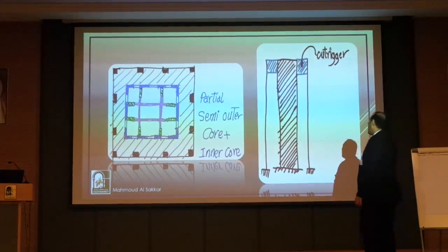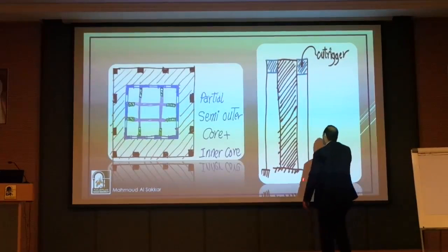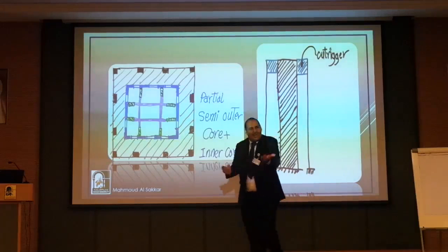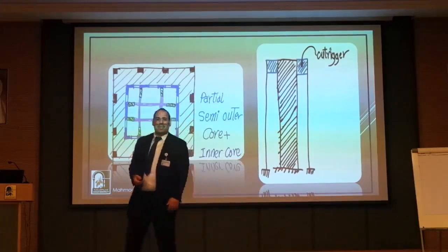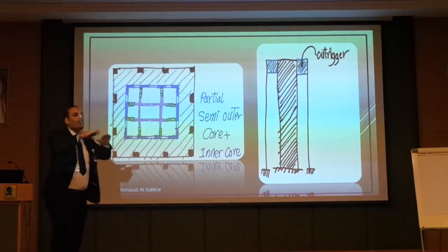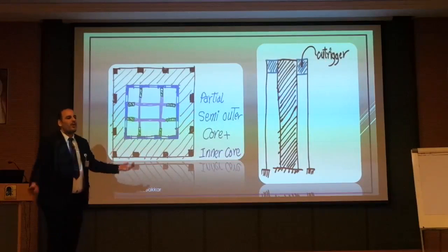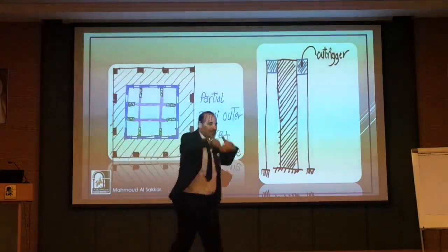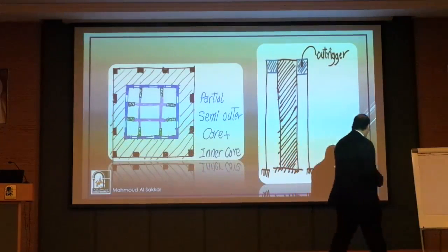Okay, one great mistake. Someone says, okay, we're going to carry tension. A column can't carry tension, there's a problem over there. How can I carry tension? No, don't be angry. Don't be worried. Don't be concerned. Why? Because the column already carries compression from the load of the floor itself. You're going to decrease the load. You're going to serve the column. The column is going to tell you, thank you. You have just rescued it from a lot of loads. Okay? So that's called an outrigger.